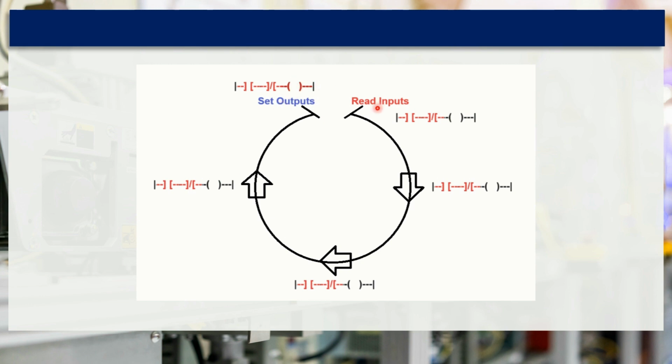It goes and does this, the next scan, does the exact same thing. It reads the inputs, doesn't care what happened the last time. Things change out in the real world, looks at the inputs, starts to solve the logic, and then finally sets the output again.